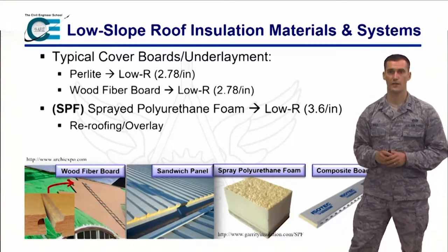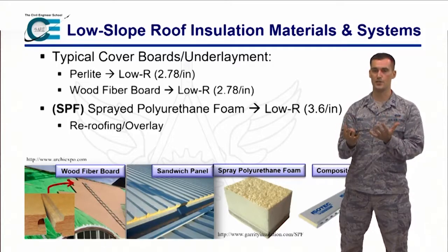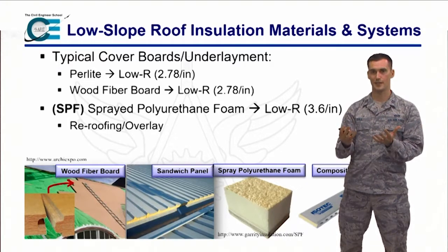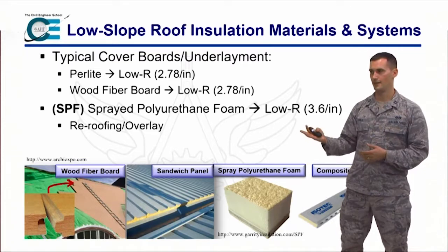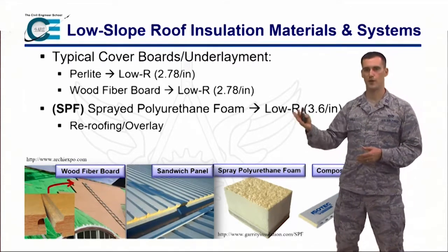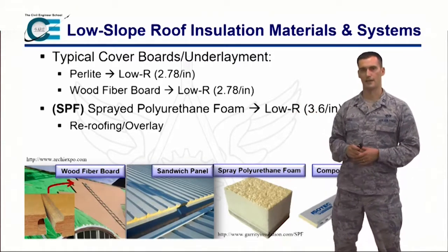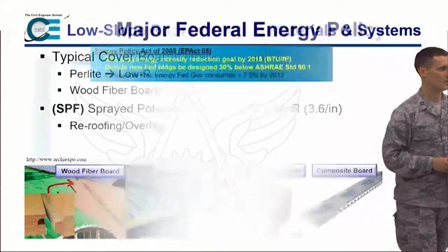Forks, we had an issue where the control tower, there was thermal bridging going on there. The facility's already been built. You can't rebuild the roof, and that's when these are a good application to come in and spray the underside of the deck in order to prevent some of the heat transfer that's going on.